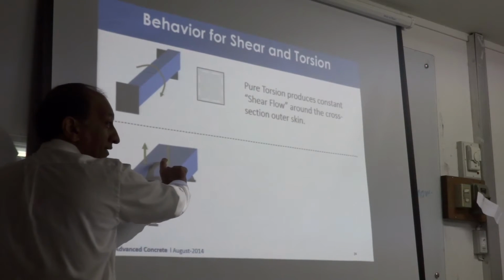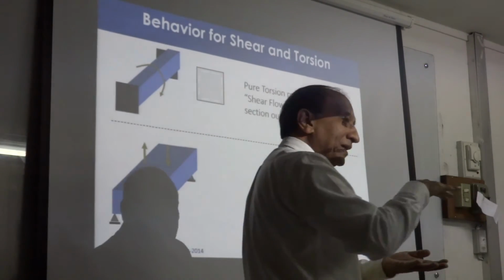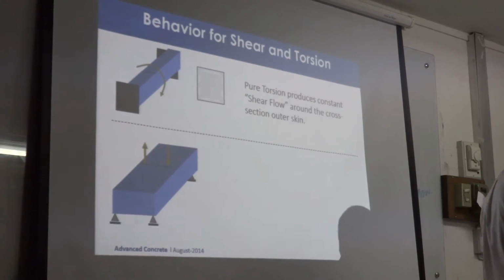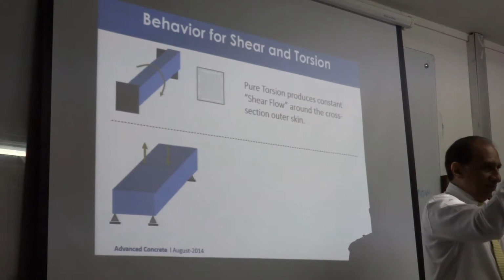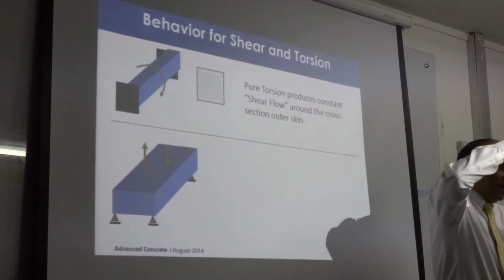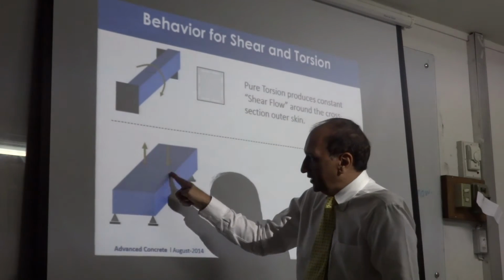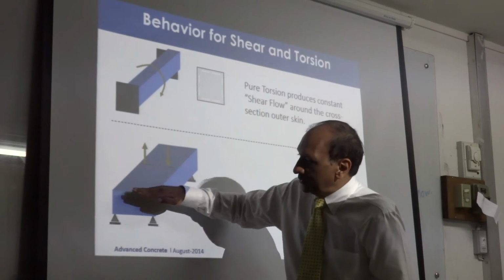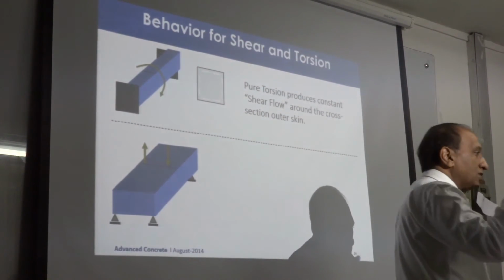For a beam, normally we always think it to be positive or negative. But in an earthquake, it could be positive or negative at the same location because the direction is changing. Okay? So based on that, we need to calculate the reinforcement and provide it at the top or bottom, or top and bottom. And sometimes we also need reinforcement in the middle.